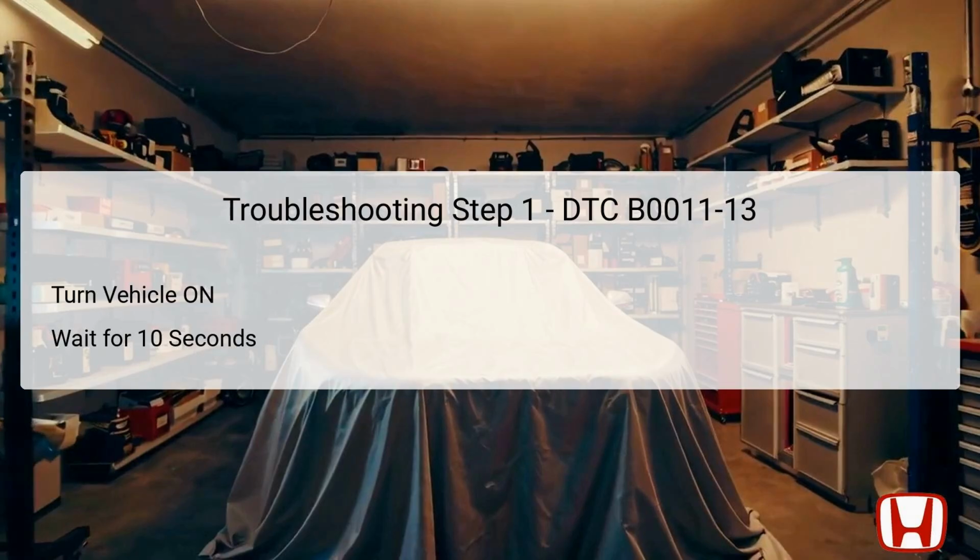The first step in the troubleshooting process for DTC B0011-13 is to turn the vehicle to the on mode and allow it to sit for 10 seconds. This action powers the SRS and ensures that the system is fully operational prior to beginning any diagnostics. It's essential during this period to check for any immediate errors that may appear in the system's memory.